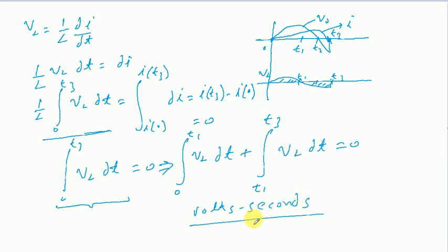And this is basically that volt-seconds principle that we have had a quite detailed discussion upon in the previous lectures related to DC-DC converters, and these principles stand true over here as well. In terms of area, we can specify it like this: if we label this one as area A and this one as area B, from 0 to t1 and then from t1 to t3.